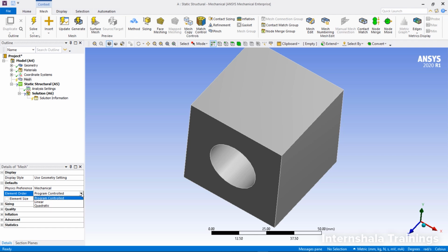as it was found that there was not much difference in the accuracy of the solution between the linear and quadratic hexahedral elements, and anyway the solution time for quadratic hexahedral elements is much longer when compared to linear hexahedral elements. That is why it is commonly followed in the industry.